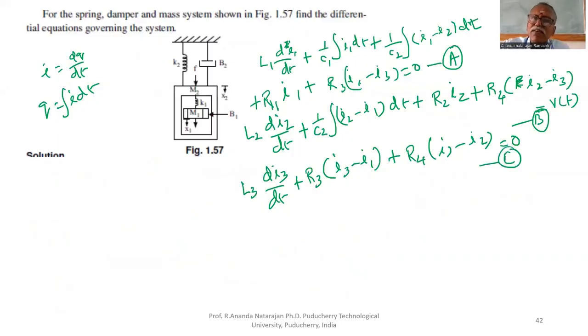You see that in the first equation, I1 minus I2, therefore first loop and second loop are adjacent. In the same first equation, one more, I1 minus I3, therefore first loop and third loop also are adjacent. Here, I2 minus I3: second loop and third loop also adjacent.